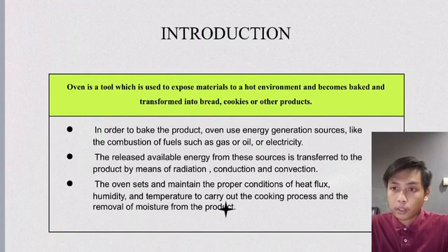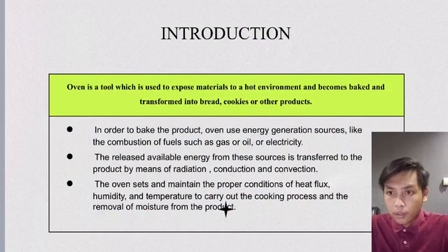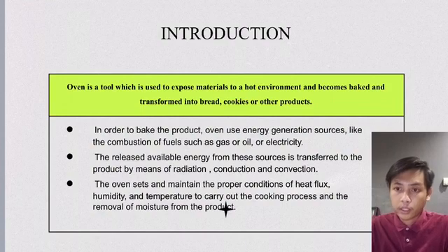Some of the skills that we will learn are creating, constraining and dimensioning a sketch, creating and editing solid-based 3D features from a sketch, placing and constraining connection paths in assemblies, obtaining model measurement and property information, creating presentation files, exploded views, simulating motion in an assembly, creating and editing an assembly bill of material, and creating and annotating drawings and views.